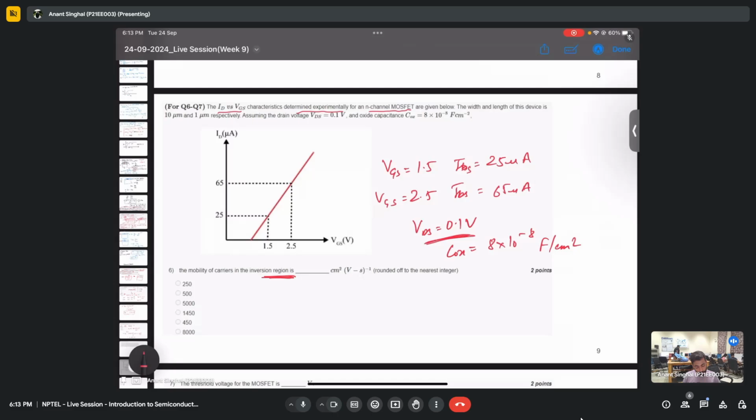So what it is showing is even if the VT is at highest 0.5, VDS will always be less than VGS minus VT. That makes the transistor in linear region, right? And for linear region, we have two different equations given what is IDS for a particular VGS. So can we have two different equations and calculate the mobility?